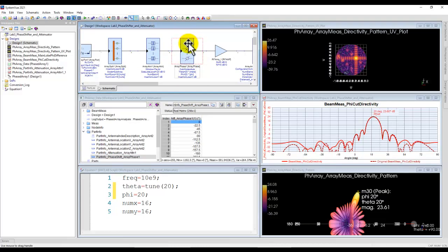Similarly, the phase shifter component will have phase settability error. That means if you need 22.5 degrees, you may not get exactly 22.5 degrees, right? You will have a certain plus and minus tolerance associated. Also, each phase shifter will have its own insertion loss, and that insertion loss will vary based on the frequency and the state you are referring to.